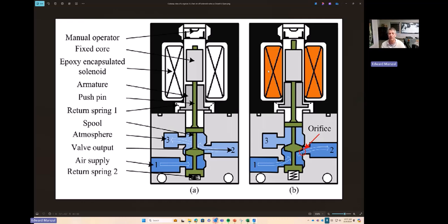So look at your data, because it's going to consider how you design your plant, your ambient environment, how you're doing your maintenance practices. In the meantime, you can use vendor data, you can use exida generics, Kenexis generics, whoever's generics, but always be dubious, because the data sources that the data came from have orders of magnitude spread in those data sets.